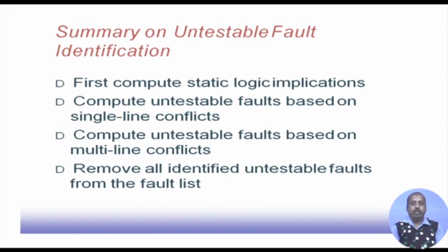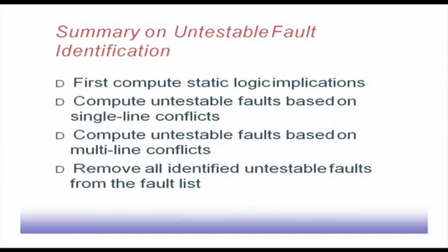Then before submitting the faults to the ATPG tool to generate test patterns, we remove all those faults from the list of faults given to the tool. That way this ATPG algorithm will have a much smaller number of faults for which it has to generate test patterns. So, that will speed up the operation of the ATPG.